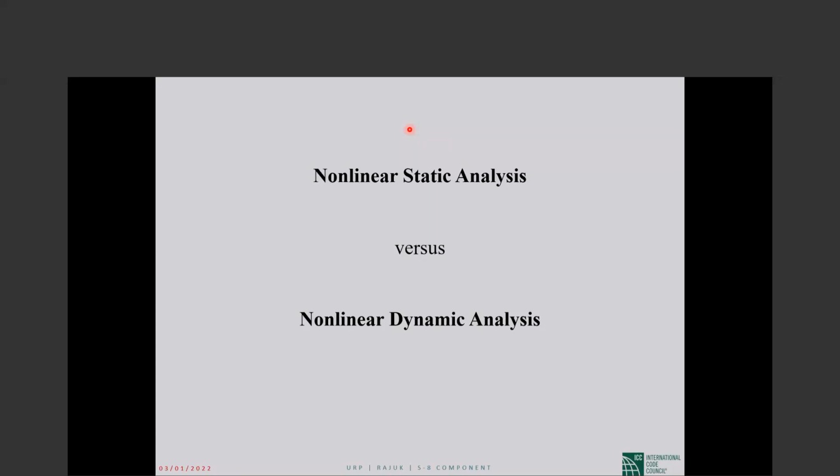So comparing the results of nonlinear static analysis with nonlinear dynamic analysis is not useful, because the results of nonlinear dynamic analysis are not reality. There is no reality there, and any difference in the characteristics of the earthquake at the same level changes the result. But at least in nonlinear static analysis, there are a couple of points where they can put a specific level of conservatism, such as the calculation of performance level, the load distribution that is being used, and so on.